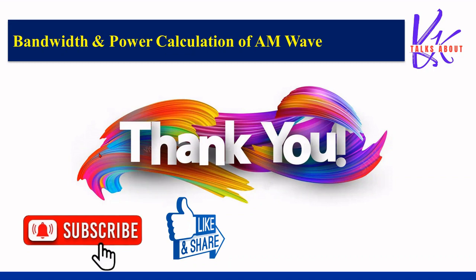The bandwidth is twice that of your message signal, and the power utilized by your AM wave is given as Pt is equal to 1 plus mu square by 2 into Pc. That is, if the modulation index is 1, then 1.5 times that of your carrier power is your total power. In other words, we can say that the carrier is utilizing 2/3 of the total power, that is 66.6% of the total power. So with this, we conclude this topic. Thank you.